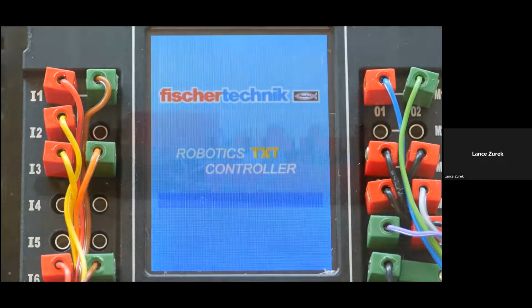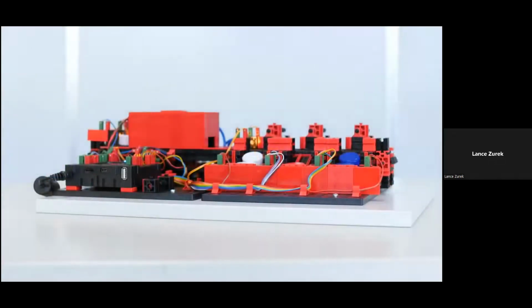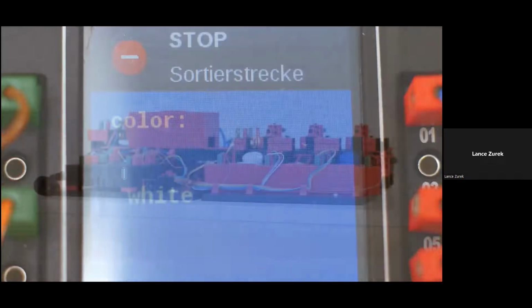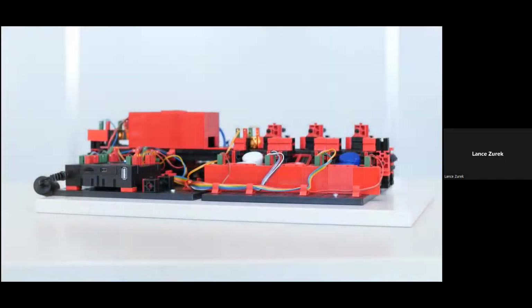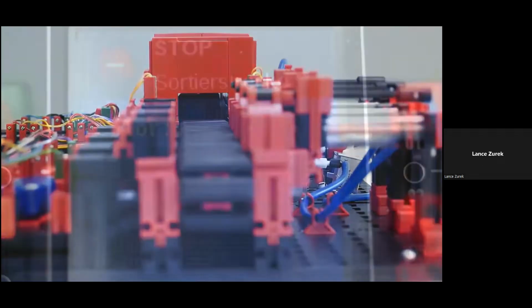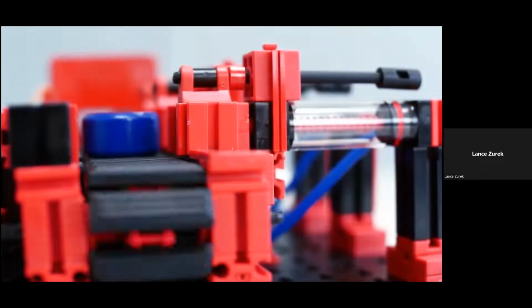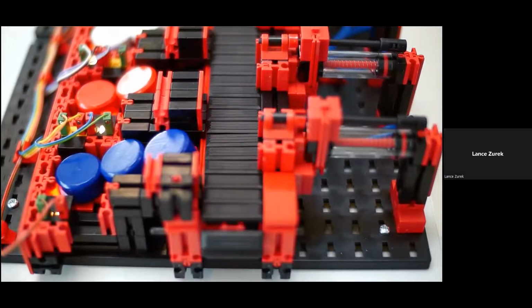The dimensions for the model are approximately 20 by 14 by 12 inches, and it has a weight of just about 10 pounds. Now, as with the models we've looked at before, the standard 24-volt version again has a relay board for motor polarity reversal, and both a multi-pin connector, 34 pins with a grid of 2.54 millimeters, as well as additional PCB terminals with push-in connections for all inputs and outputs. Again, you will need to provide the PLC and the programming of your choice.